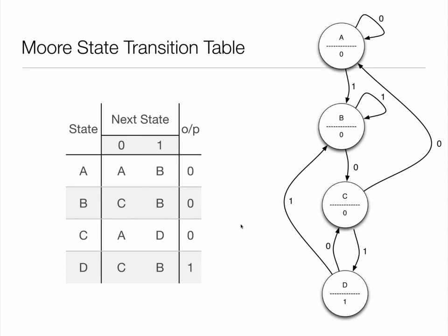If you can, use these slides to come back to this so that you can pick up the format, because it's going to help in a minute. If you draw them like this. Okay, so for each state there is a unique output. So we've got this output column here. That's different with the Mealy machine.